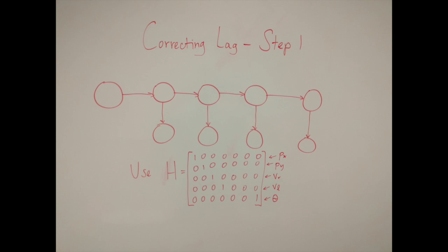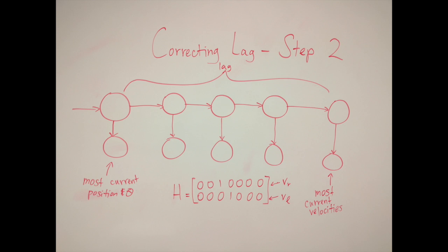The updated mu and sigma values that we obtained in this way are the ones that we saved from iteration to iteration. We then iterated through 4 more delta t's using our most current velocity values in order to remove lag. Finally, we extracted position and orientation from our mu t plus 1 in order to better calculate our attractive forces and our robot's need to turn.